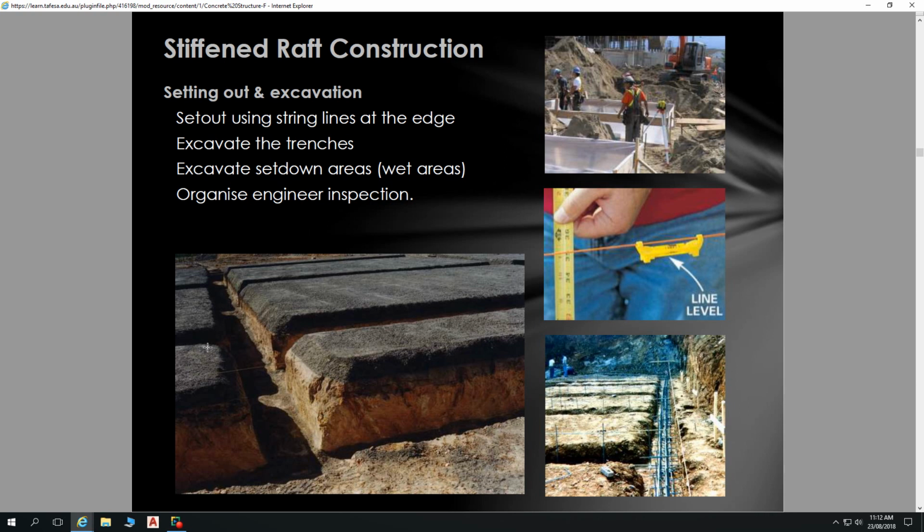It can be shaped nicely, and that's important because this is some sort of fairly rough looking trenches. If our trenches are really rough, we need to order more concrete to ensure that we've got enough to fill in all these little gaps, all the bits that we didn't calculate for. If we've got really nice looking trenches, we can order less concrete because we don't have all these little gaps that need to be filled, and we're not going to be using up our excess concrete beyond what was designed for.